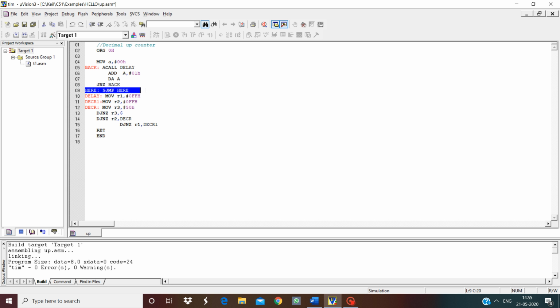And next we are having the instruction SJMP here, where the label is given to the same instruction. SJMP is an unconditional jump. So the control stays in this loop until I terminate the program. In some editors or monitor programs where I'm not having the option to terminate the program, this instruction is used to terminate the program. Okay, so this is the case.